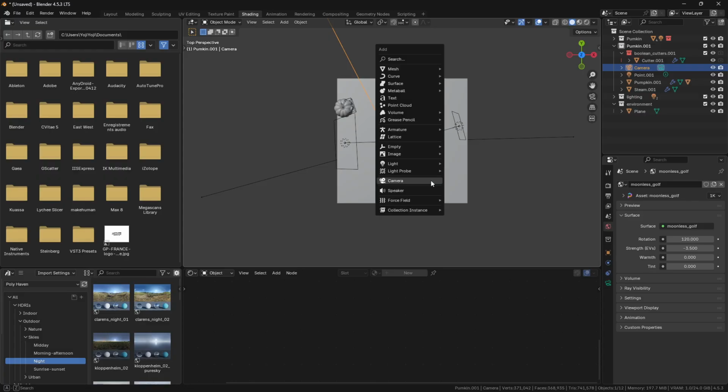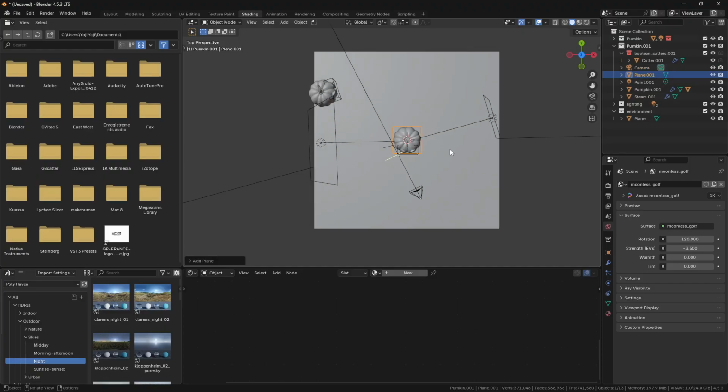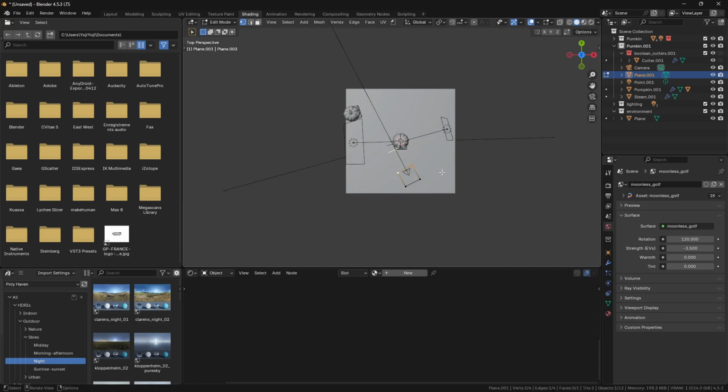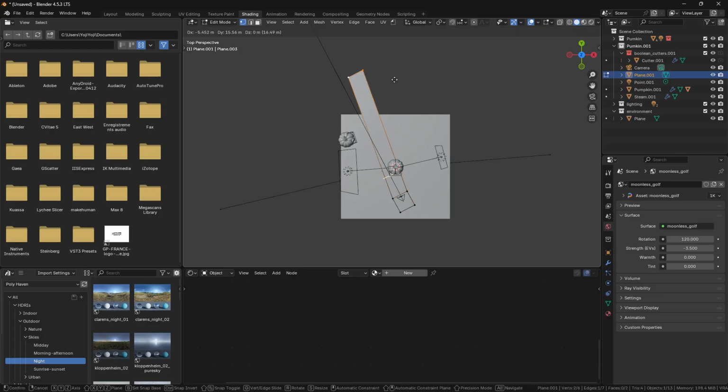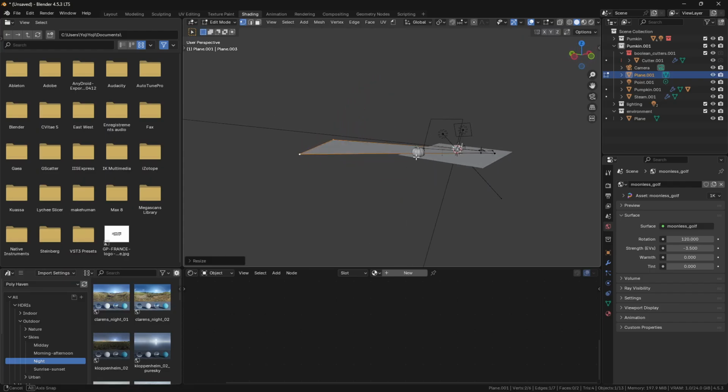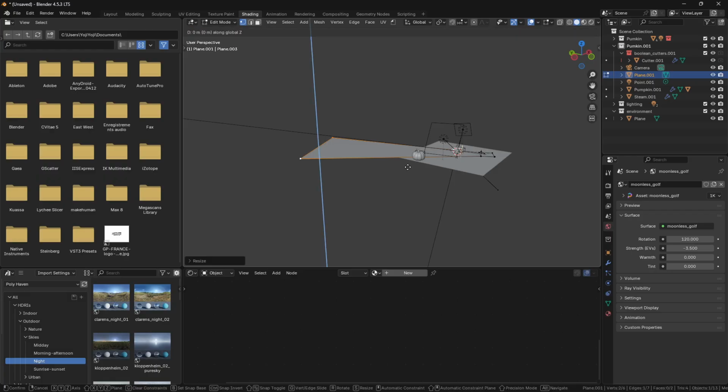We just go there with a mesh, and in edit mode, I will make a rotation like this, put it near the camera over there, and extrude that until it goes far, somewhere here. Scale it up till you have something like that.